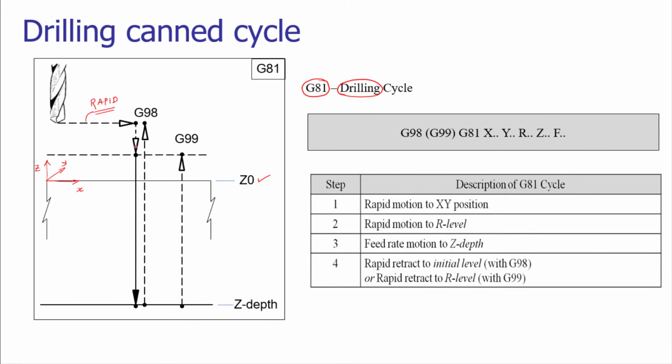Afterwards, it is approaching the desired position. So let us consider that at this position, the tool has to carry out the drilling operation. When it is approaching the top portion of the work part, that approach may be converted into two modes, that is the rapid mode and the feed mode. Rapid mode would be used to improve the productivity, to do the faster operation.